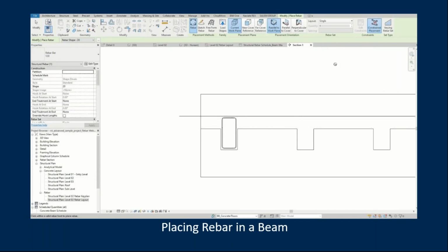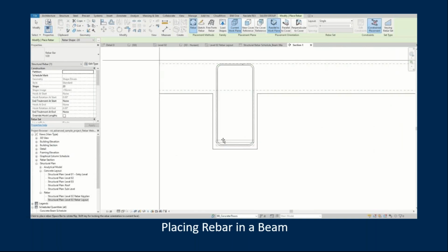So after the link, I'll go in with a longitudinal bar. And I just want to check that I have the correct plane. So you can see whichever cover setting you move to, that's where the bar will sort of orientate to. So those green dashed lines, that's the cover. And you can toggle between the different planes with the space bar as well.